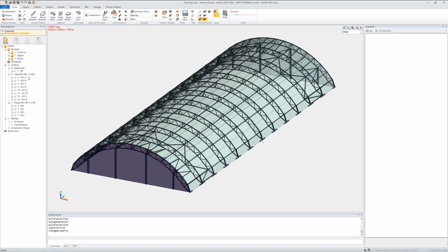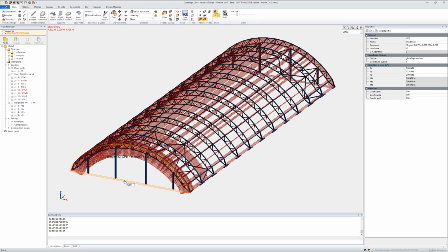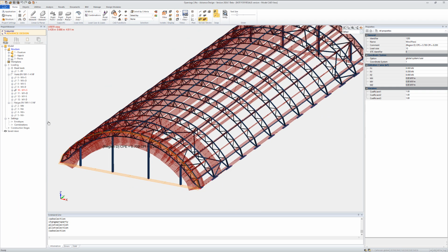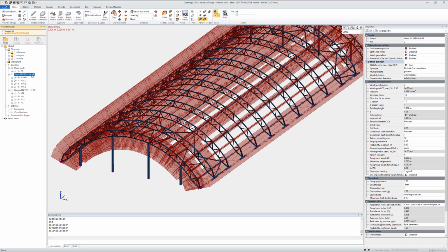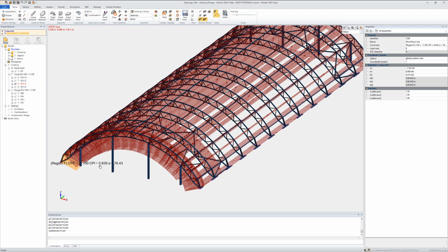And in this case, instead of having, let's say for this direction, a zone D with a 0.7 pressure coefficient, first I won't get any wind force there because the face is completely open, and the internal pressure coefficient will be taken for this direction as 90% of the CPE we don't have. So it will be 0.9 of 0.7. This is why for this direction we have a CPI, internal pressure coefficient, of 0.63.